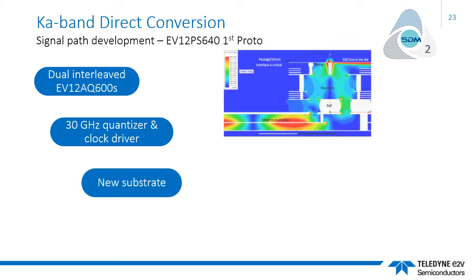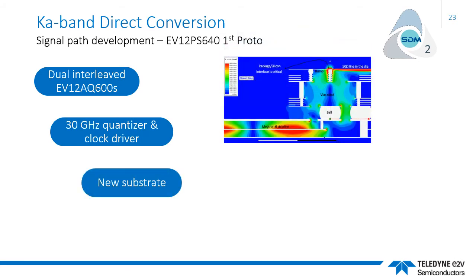Firstly, a new high-frequency substrate material was identified, and multi-chip techniques were used to minimize parasitic component effects. Gone are any wire bonds in favor of shortest path bump die connections. Moreover, to ensure optimum dynamic performance, a full high-frequency electromagnetic study was commissioned, as illustrated here, to ensure matched impedances throughout, and that a highly functional and quiet design resulted.